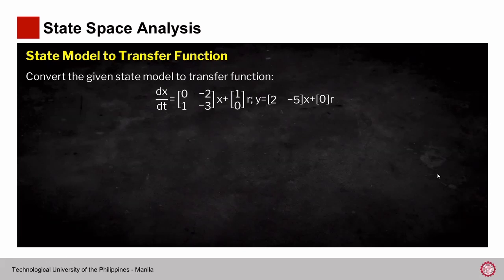And what is that? The formula to get the transfer function is nothing but Y of s, and usually Y kasi yung output. Kapag state matrix, Y of s upon U of s. So actually, U of s yung gamit nila. So this is nothing but C, matrix C, the output matrix, into sI minus A inverse, times B.